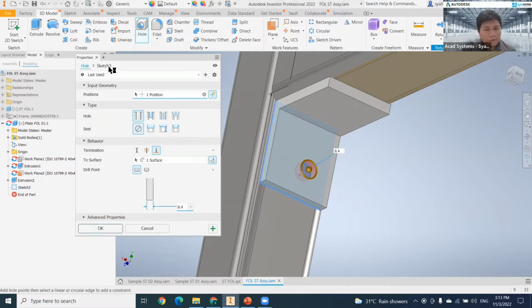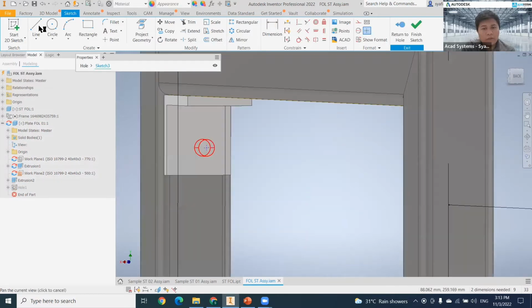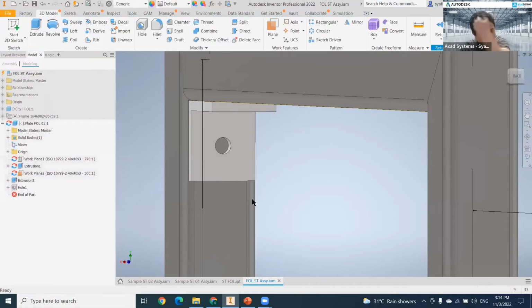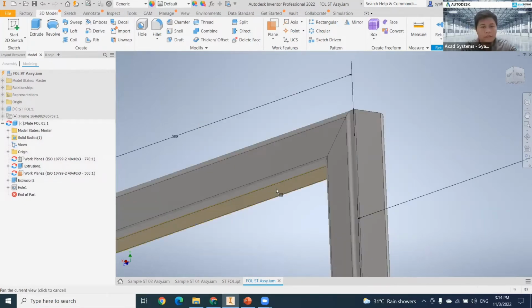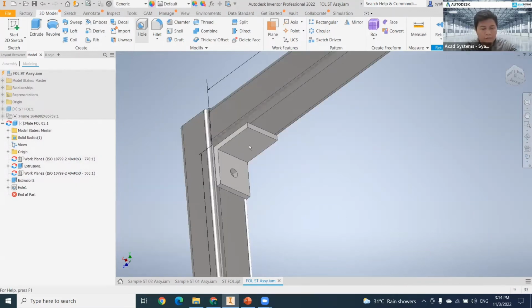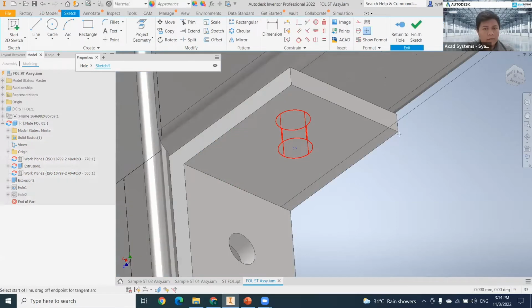After doing the selection, now you can edit the sketch. So click on this area, sketch. Over here, you are able to move your sketch point, or you also can do something like this. Another line. Okay, use coincidence constraint here. Click on this midpoint and this point. Finish sketch. Okay, then this object is already done. Again, visibility. So just repeat the same process. Since this one has two different planes, we need to do it twice. So again, go to sketch, select the surface, which is the top one, and draw some line to get the reference for the midpoint.